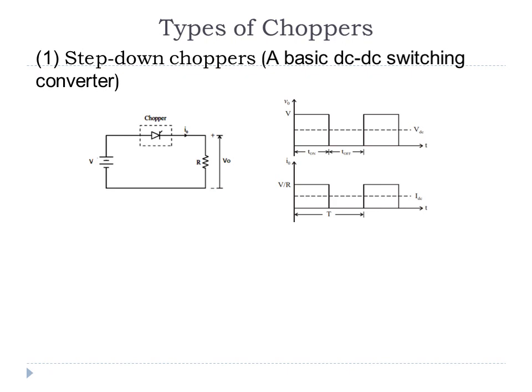When it is on, V, which is the input voltage applied here, will be connected to the load. Load in this case is a simple resistive load. Corresponding to this, the current at the output is V upon R. If it is a periodic behavior, that means the switch is on for certain time and it is off for certain time, and we take the average over a time period, it will be some level of DC voltage at the output, and similarly we have some level of DC current at the output.